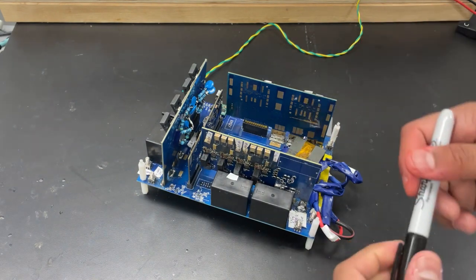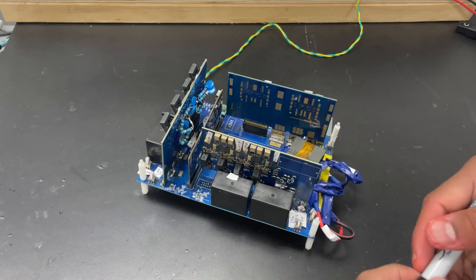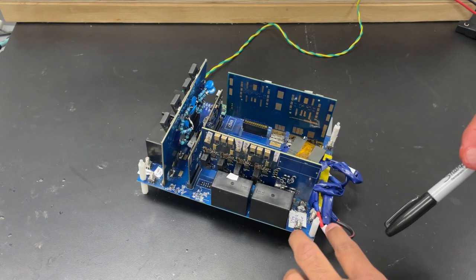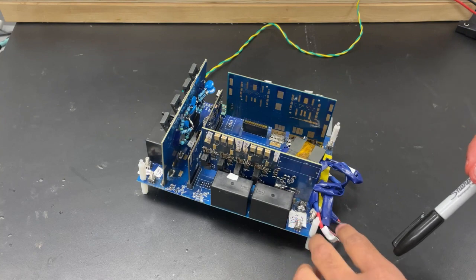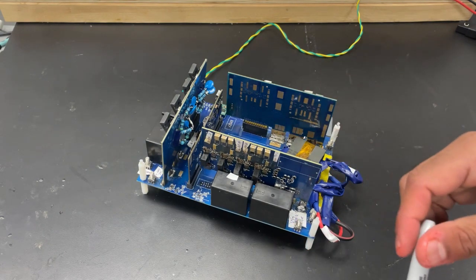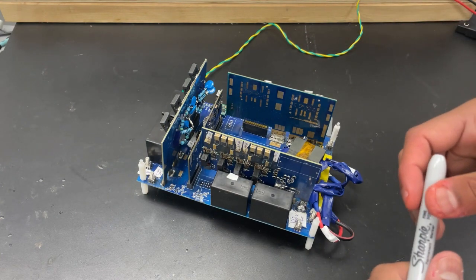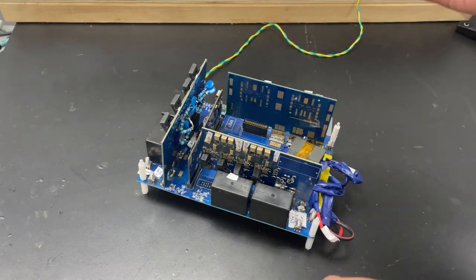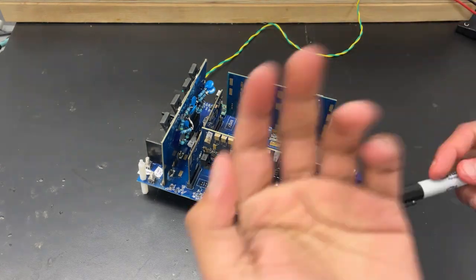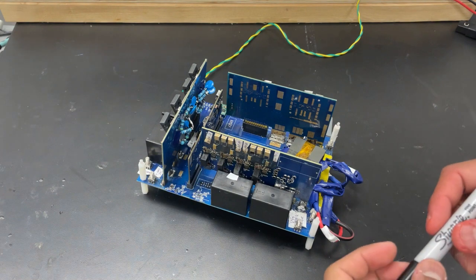The one on the left is the primary side full bridge, which has the GaN Systems 650 volt rated device. The input is provided at these two terminals, which is nominal 400 volts. The full bridge converts that input into a quasi square waveform, as is the case for the secondary as well as the tertiary side, and then provides that quasi square waveform to one of the windings of the 3-winding transformer.